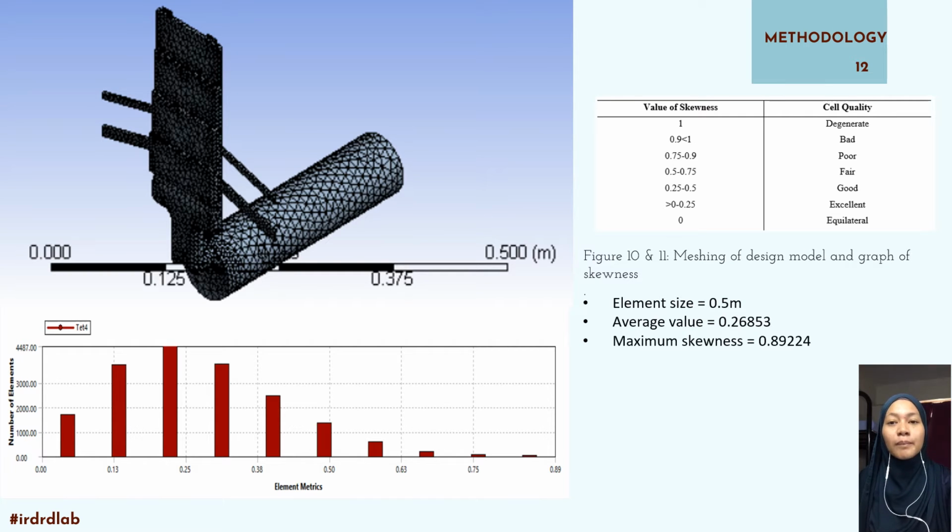Because of this complex geometry, the number of nodes on those components increased compared to the shot sleeve and biscuit. The graph is skewed to the right with a maximum element metric in the range of 0.12 and 0.23. The high-quality mesh developed is essential for generating a stable solution and a dependable CFD solution.